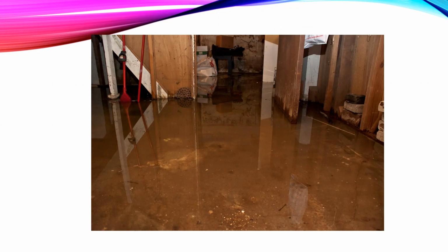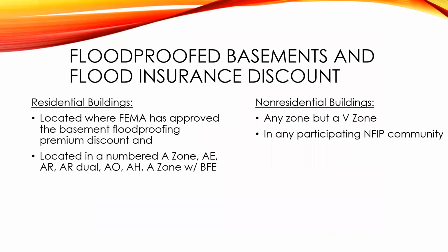We haven't seen it, again, do much for communities. It's kind of like having a sunken living room into the floor, but again, it can't be more than 5 feet below the base flood elevation, so they're not usually very deep. Again, we've had issues with this, with a lot of violations, and again, using the wrong certificate or not having a certificate or whatever the case may be. And then we've had basement flooding and failure as well, which of course contributes to structural damage.